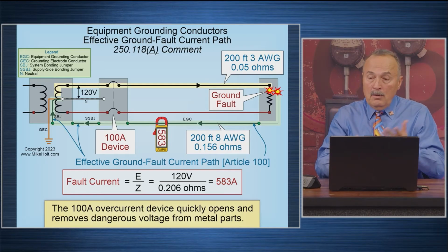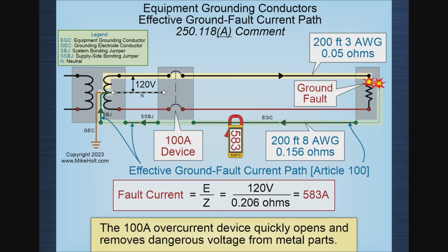Now, Eric, you're an engineer in the team here. Is that going to meet 250.4(A)(5)? Nobody knows. Because 250.4(A)(5) has no requirements in it. It just says it's got to trip the overcurrent protection. But it doesn't say it has to trip within 3 cycles. It doesn't have any requirements in there per se. So the answer is yes. It's fine. Yeah, it's fine, because we don't know.